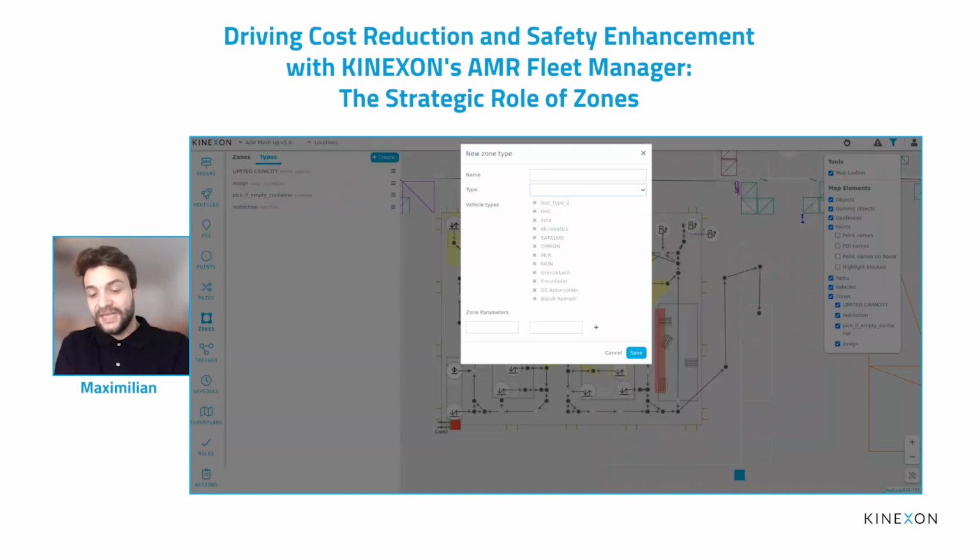And yeah, that behavior might not always be desired. So the vehicles often have a tolerance in which they can drive in an open area, where we talk about some centimeters. 5 to 10 centimeters is quite common as a tolerance to drive around the points along the line, because